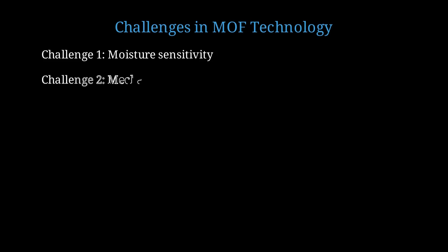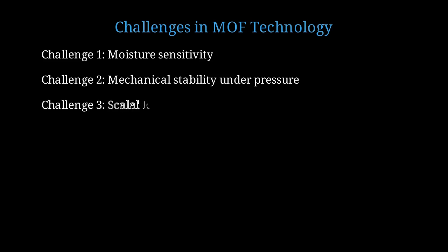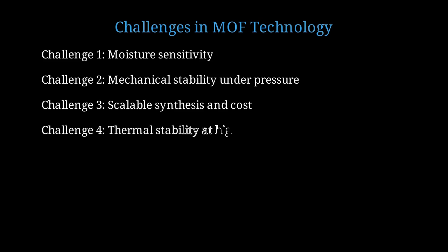Despite their promise, MOFs face several challenges that researchers are working to overcome. First, many MOFs are sensitive to moisture. Water molecules can displace the organic linkers and cause the structure to collapse. Second, mechanical stability can be an issue, especially under the pressures needed for practical gas storage applications. Third, synthesizing MOFs at industrial scale remains challenging and expensive compared to traditional materials. Fourth, some MOFs have limited thermal stability and decompose at elevated temperatures, restricting their use in high-temperature applications.